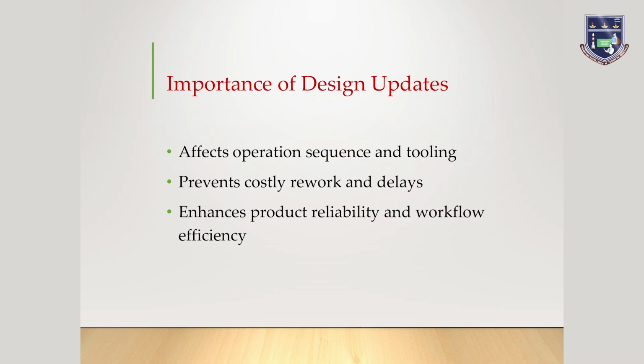if necessary. For instance, if an automobile manufacturer modifies the dimensions of a crankshaft, these changes must be reviewed in relation to the bearing housing alignment, piston clearance, and lubrication pathways to prevent mechanical failures. Overlooking such dependencies could lead to significant performance issues, costly reworks, and production delays.